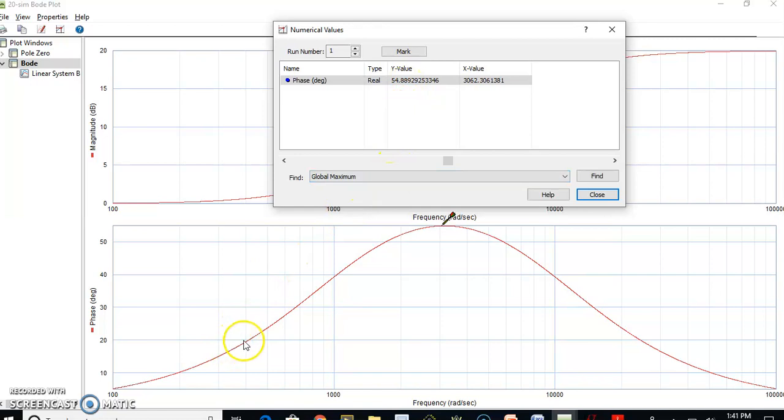So the phase angle is actually positive. That's why the name of the filter circuit is called a phase lead network, because the phase of the output will always be leading the input. The maximum phase you can lead in this case of pole-zero positions is 54 degrees. If you change the location of poles and zeros, we can certainly change this maximum positive phase with respect to the input. The output is actually 54 degrees ahead of the input at a frequency of 3.16 kiloradian per second.